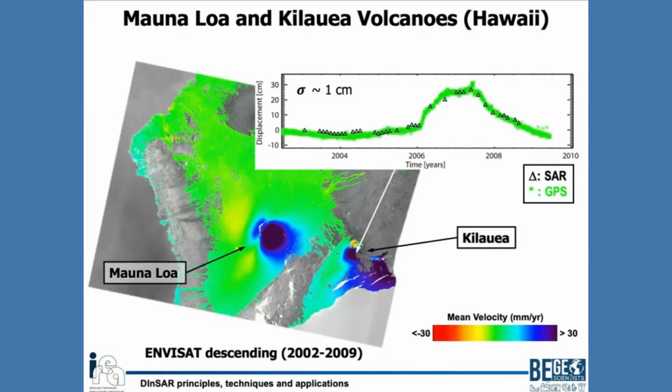So this demonstrates how powerful this technique can be, because okay, with GPS we have good accuracy, but with the DInSAR technique, advanced DInSAR technique, because you have a lot of pixels, you can reconstruct the full displacement pattern.